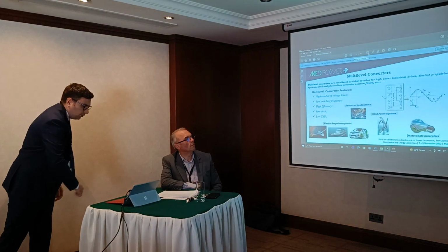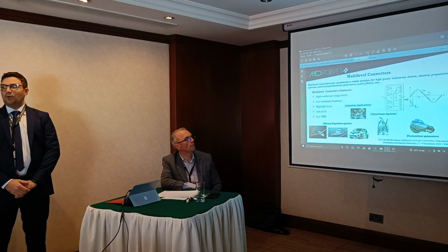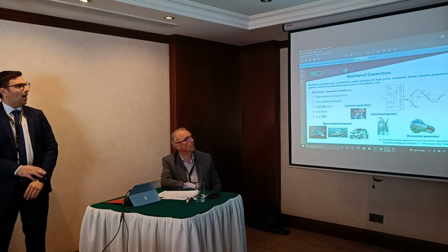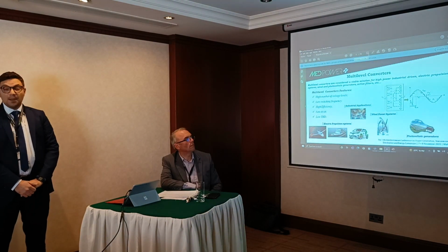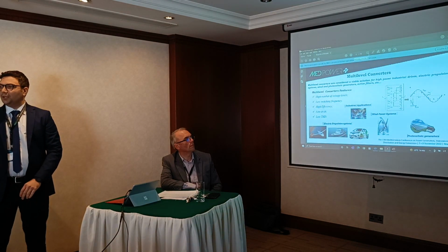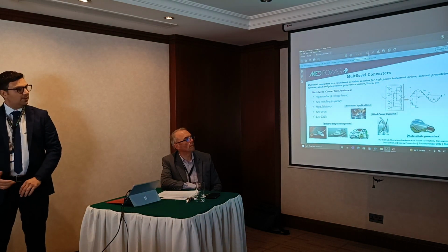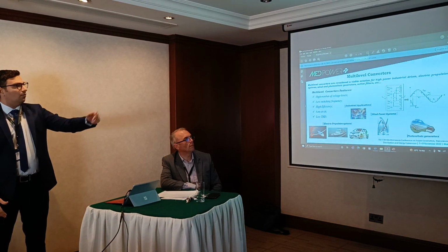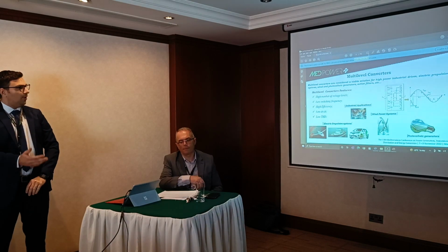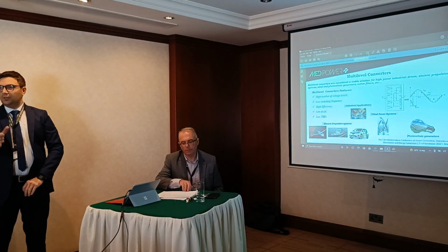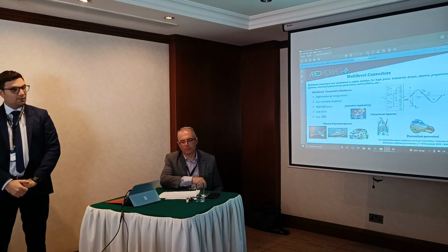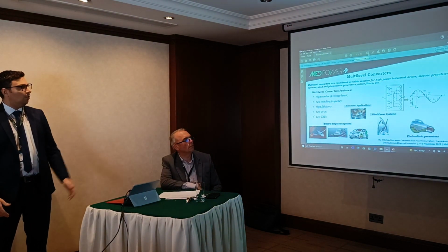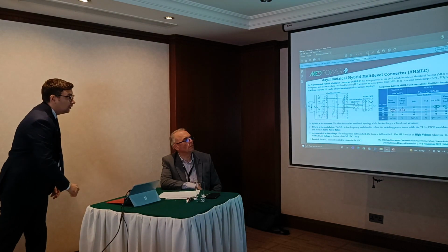Multilevel converters are used for high power, medium voltage applications, for example, electropropulsion systems, wind, and photovoltaic generators. They permit to overcome some limitations of conventional two-level converters. In fact, multilevel converters offer a high number of output voltage levels, low switching frequency, high efficiency, low voltage stress on each power device, and also a better power quality in terms of lower total harmonic distortion.